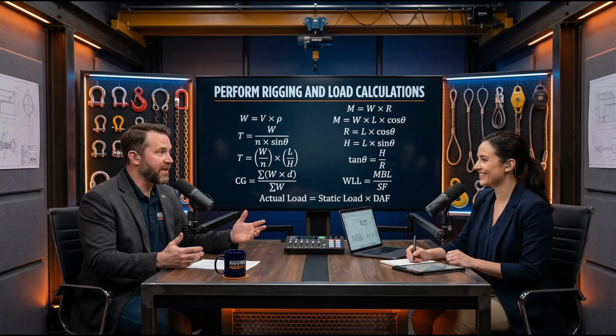Oh, so you just assume the maximum. Yes. You don't perform your calculations assuming the wood is dry pine. You run the math assuming the wood is completely saturated, pushing the density toward that maximum 1,100 kilograms per cubic meter mark. You're purposely overestimating. Exactly. You have to purposefully bloat your own calculations to build in a mathematical safety buffer.